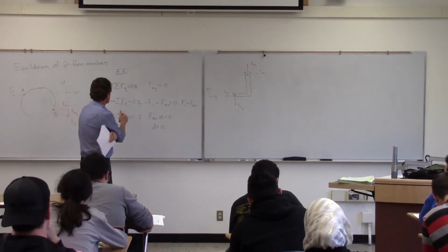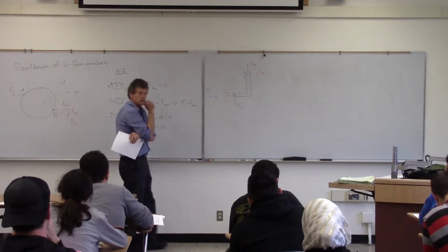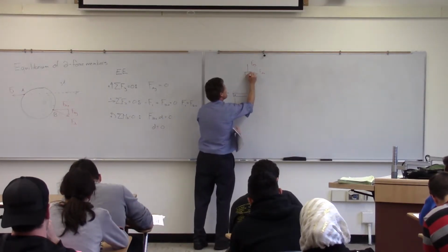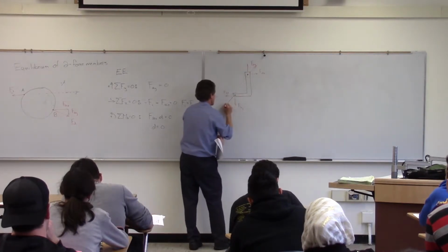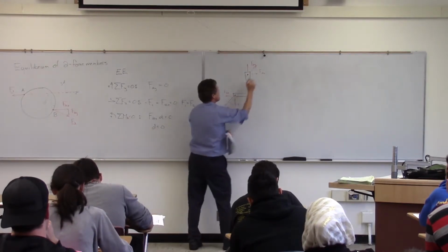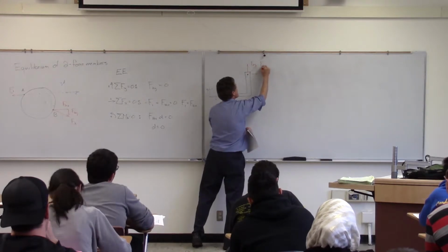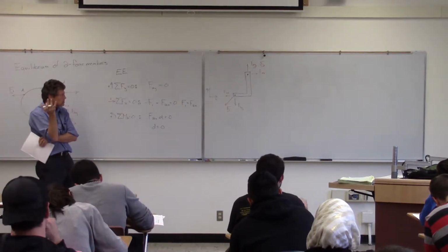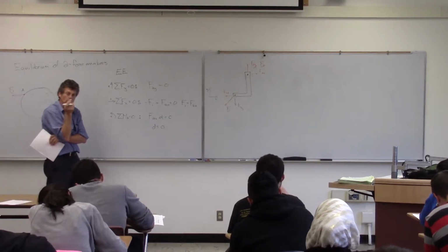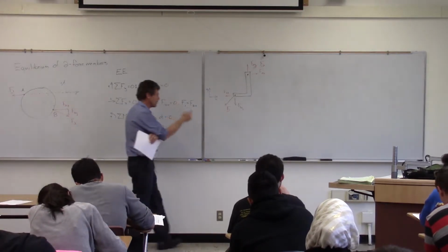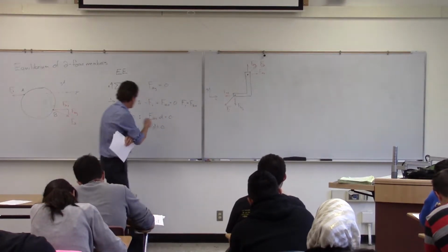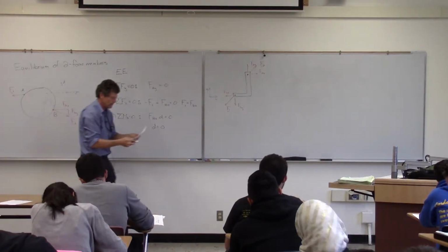If it's a two-force member, and we just got done proving that it has to act along that line of action, then what that's telling me is that I know the direction. Even though the member is not straight, if there's only two forces acting on that, then they have to be acting along that collinear line, just as we proved here.